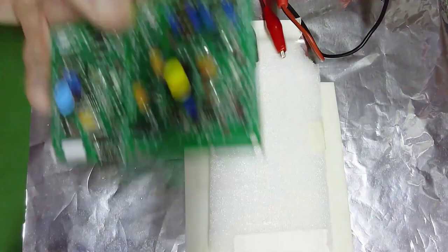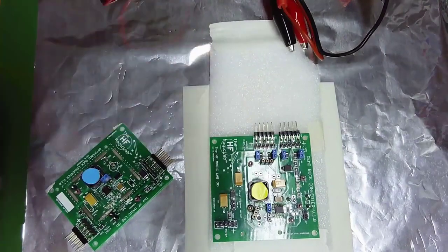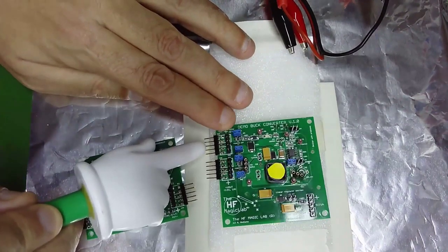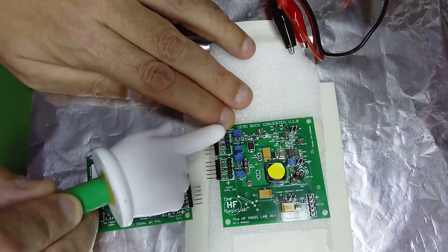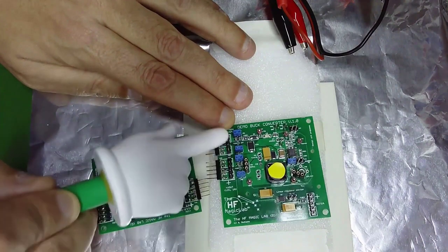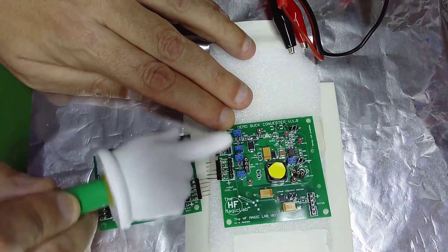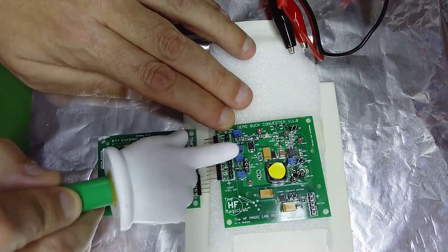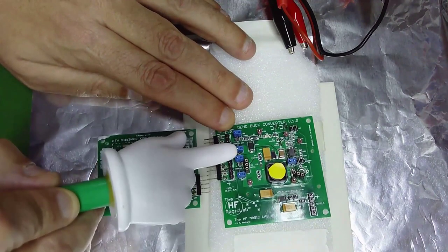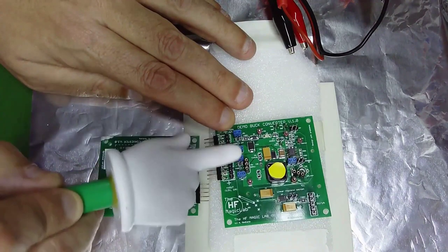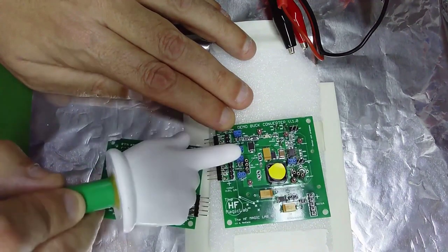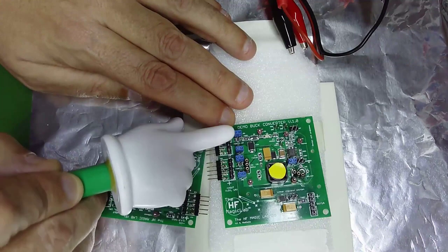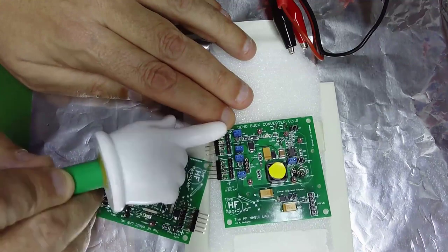Yes, I was going to interrupt you, but thank you. Sorry. This is the same. You can see here the original board, where you can see here the input voltage and the output voltage. So that means that the input and the output are one close to the other. You have the filter. Between these filters, they have a strong coupling. The only possibility is to introduce in the middle some kind of shielding, no? Or some kind of orientation that minimizes this coupling. This effect of coupling is increased if you use potting. If you use potting, the potting is usually a dielectric material with a constant between 3 and 6. So you will be increasing the capacitive coupling between the components in the input and the output.